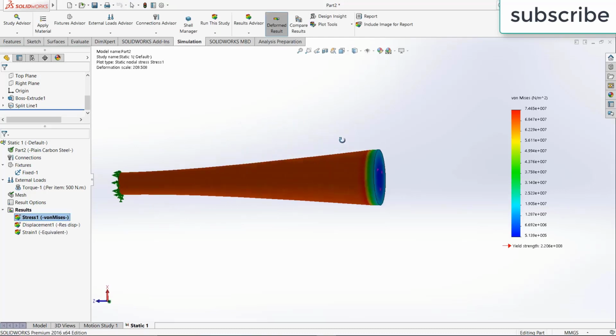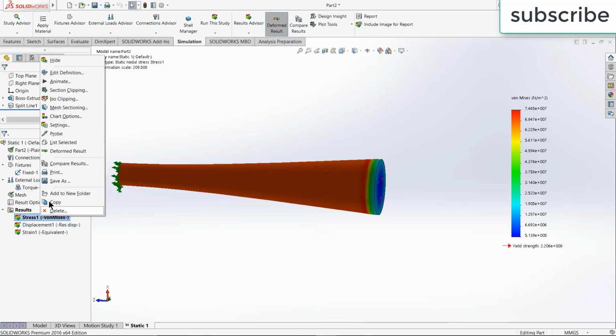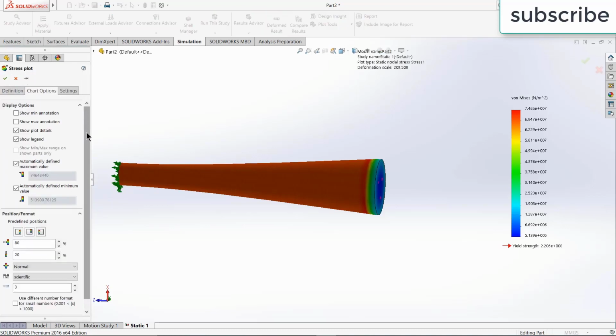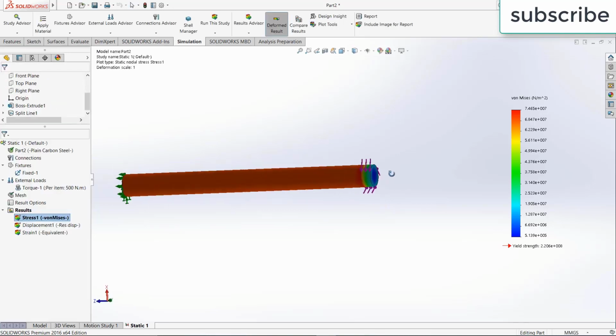After simulation, you will see this kind of result. The first question that arises in your mind: what the hell is this? And why is it so big? So basically, when you do a stress strain simulation, SolidWorks shows the results 500 times or sometimes 200 times higher than the original. For example, if I right click on it and go to chart options, go to definition, you see this is automatic. This is 209.507 times the original. If I click on true scale and click OK, this is the original.